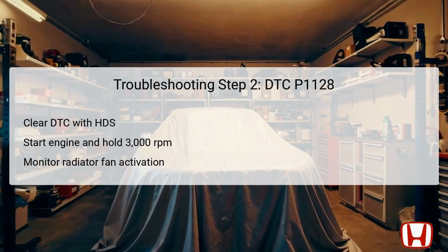Maintain this speed until the radiator fan is activated, which serves as a benchmark for engine operation temperature. Letting the engine idle afterward allows for further observation of the MAP sensor's behavior under controlled conditions. This process is critical because it can reveal whether the initial issue is transient or if the MAP sensor maintains a low signal in subsequent checks.